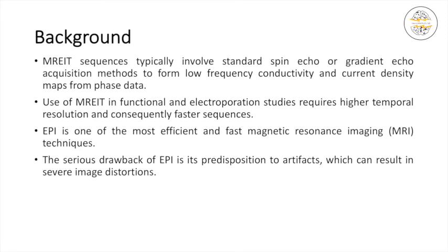We are developing a technique known as MREIT, which stands for Magnetic Resonance Electrical Impedance Tomography. MREIT is a method of imaging low-frequency electrical properties of tissue. This is done by examining magnetic flux density created by a known applied current that has been encoded in MR phase images. The available component of this magnetic flux density, the Z component or BZ, may be processed to produce current density, electric field or conductivity images via Maxwell's equations.